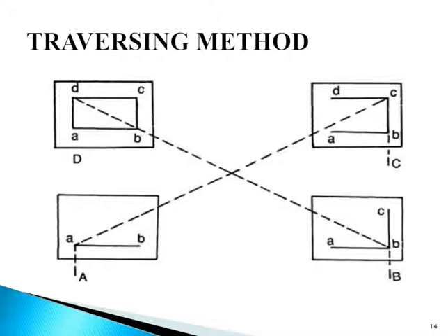Okay, so let us understand it with the help of the figure. Suppose capital A, B, C, D are the traverse stations. So first of all, the table is set up at station A. A suitable point small a is selected on the sheet, we can see it in the image here, in such a way that the whole area may be plotted in the sheet. We have to cover all this region, so according to that we have to select point a.